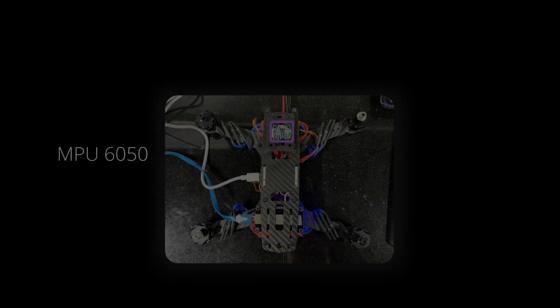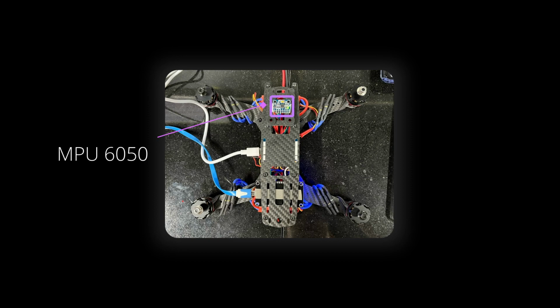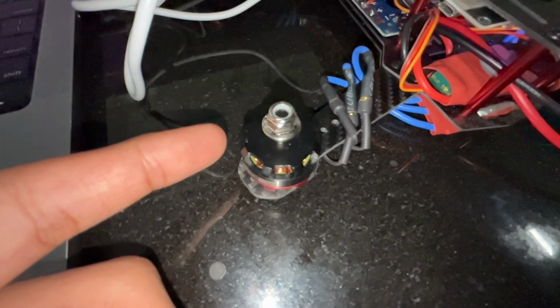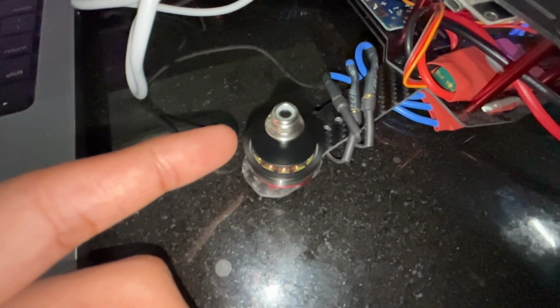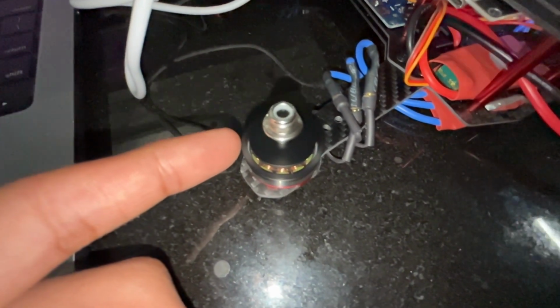In step 1, the MPU 6050 module includes a 3-axis gyroscope and a microprocessor for managing serial communication and data storage. By measuring acceleration due to gravity along the 3 axes, we determine the tilt of the drone. In step 2, we verified whether the ESCs were working properly and that the motors were rotating in the intended direction, along with the working of the application and the gyroscope.